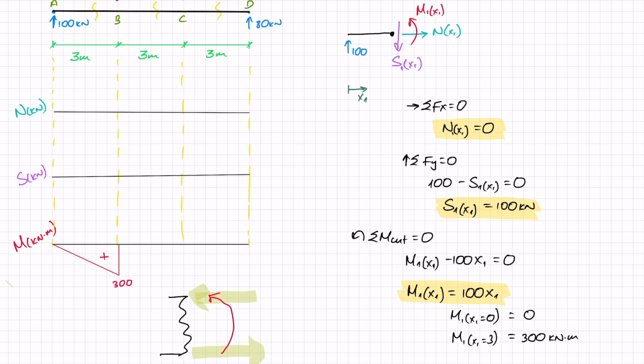If I go back to draw my shear, I got that my shear was 100 kilonewtons plus, so I can just go up here and I see that I have a straight line right until here, and that is 100 kilonewtons, and that is a plus. And although I got 0 for my axial force diagram, whenever you're asked to draw something, do always draw it.